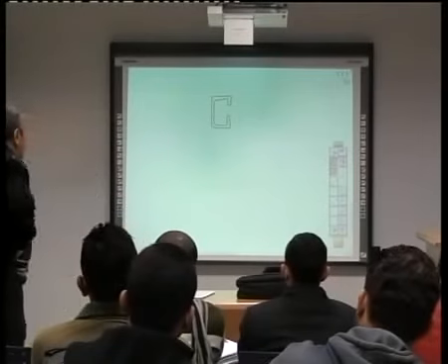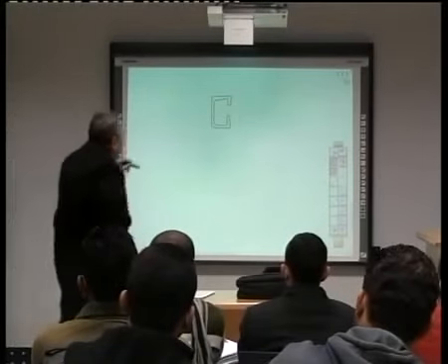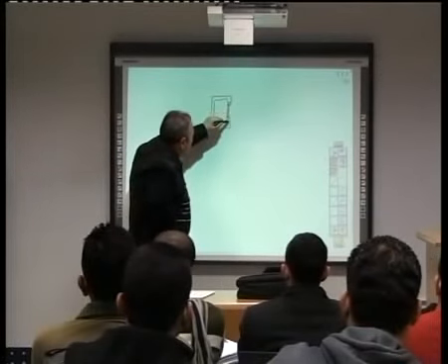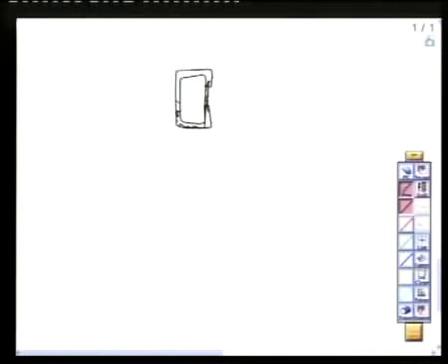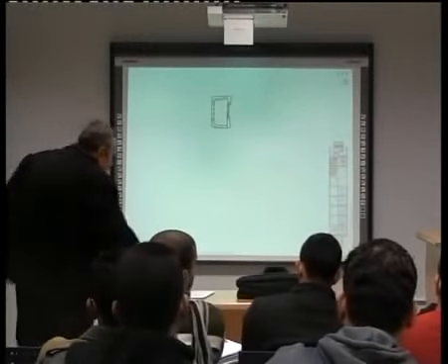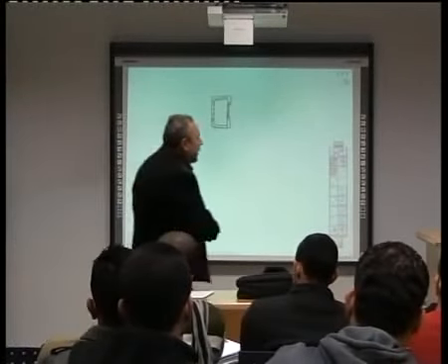So he was advised, in order to decrease torsional deformation, to make this section what? Closed. After doing the classical solution, and the classical solution brought the same answer as the finite element solution, NASA approved his research proposal.